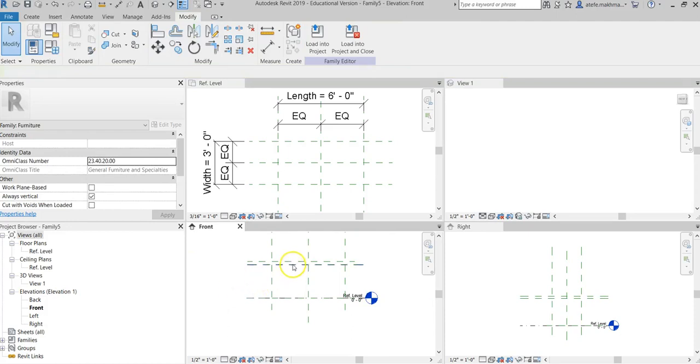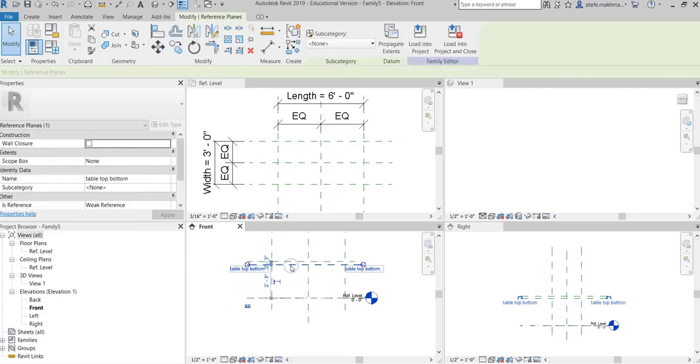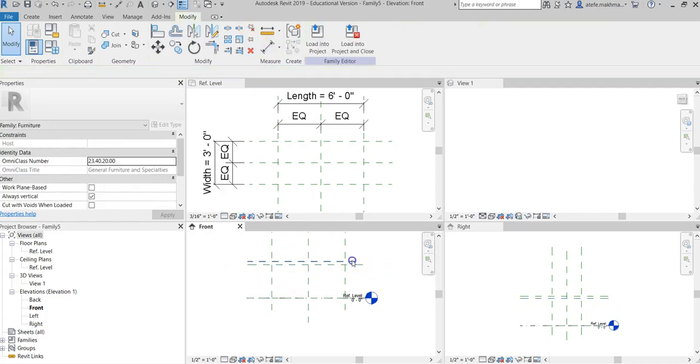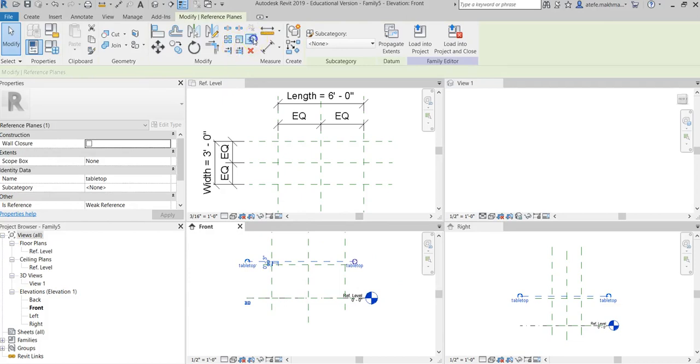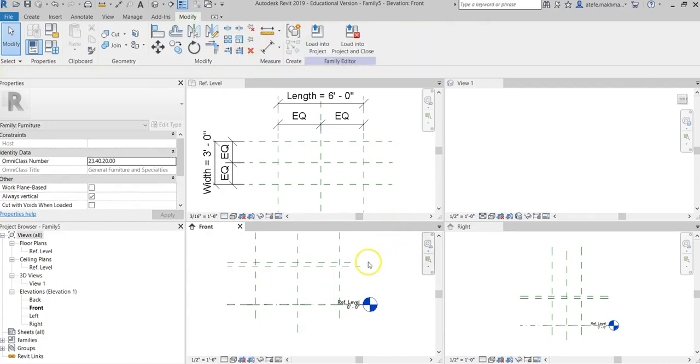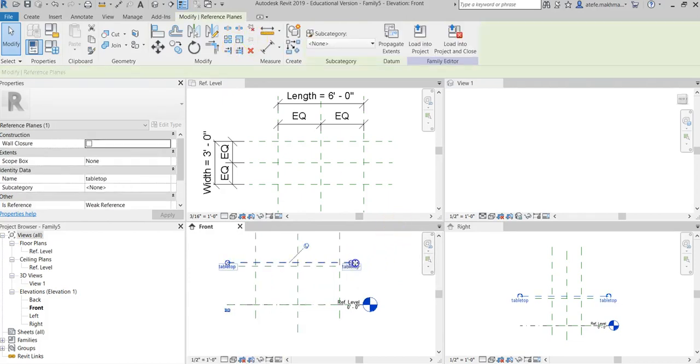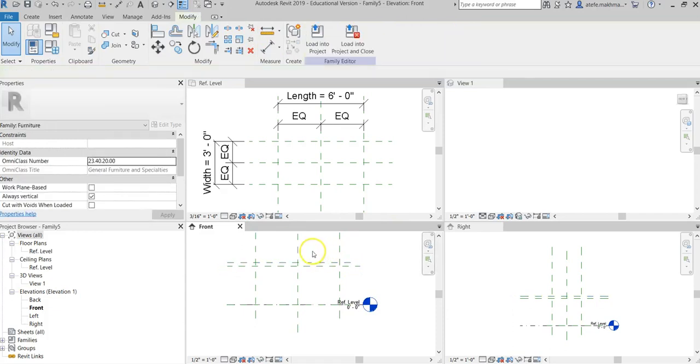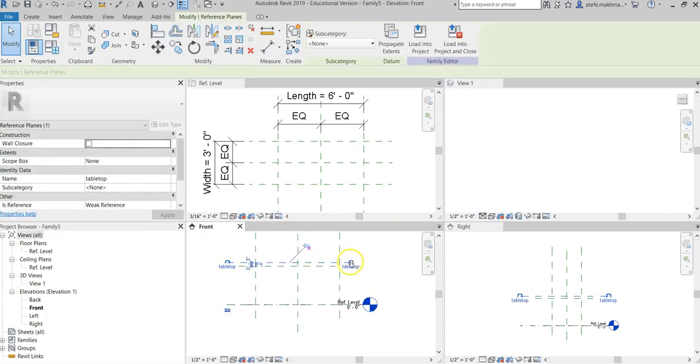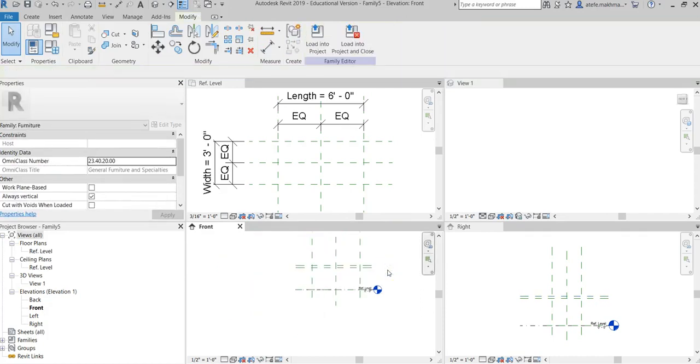And these two, actually, I don't want them to move, right? So I'm going to pin both of them. Make sure they do not move. This is not what I want to flex. I want the height again to be the same. So I'm going to lock them. Before unlocking it, I can extend this so I have them exactly the same size. So always try to clean up your model.